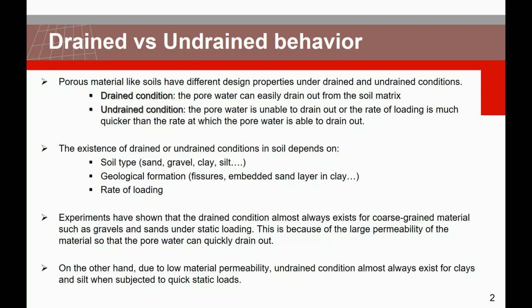The existence of drained or undrained conditions in soil depends on the soil type. Is it a sand, gravel, clay, silt? It depends as well on the geological formation, such as fissures, embedded sand layers, etc. It depends as well on the rate of loading.